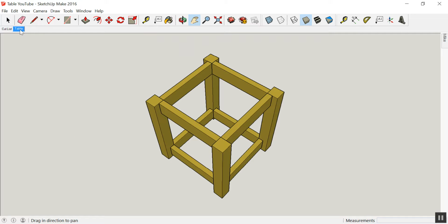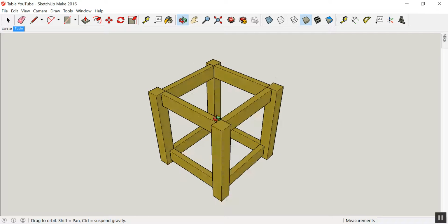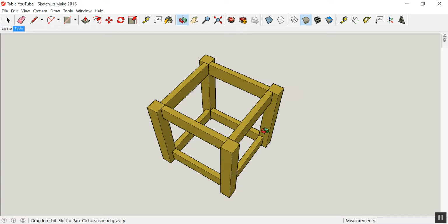And then I would take that into my shop. And for 3 inches here, we're probably going to start with a 3.5 by 3.5, which is out of the Menards or whatever, standard stuff, and then plane it down or run it through a bandsaw or something. And then for the 1.5 by 4, I would probably start with, we have access to rough sawn lumber. So I would get some rough sawn lumber and then just clean that stuff up down to where I want it to be.